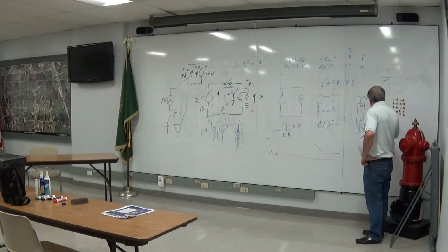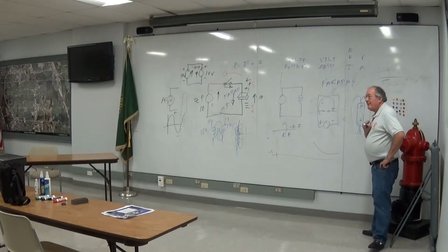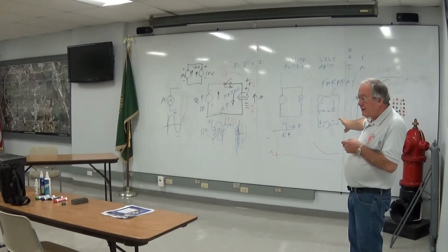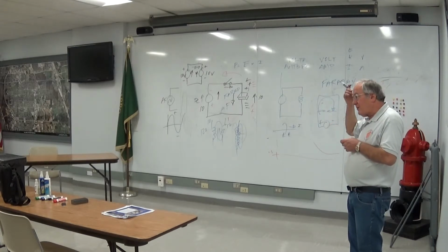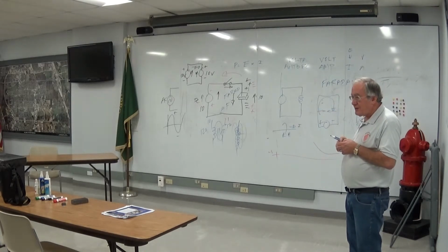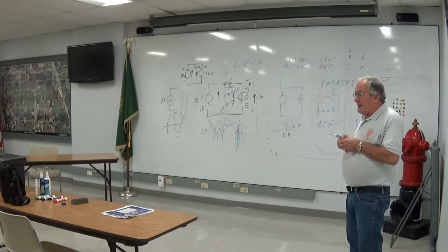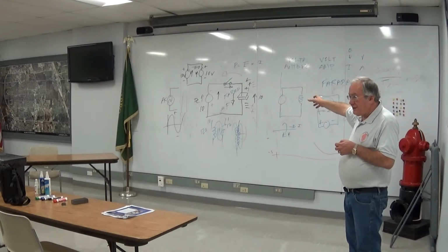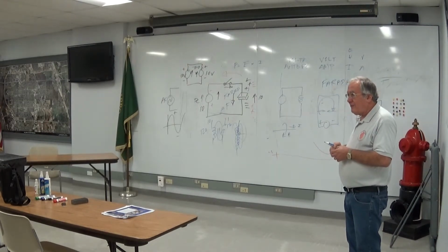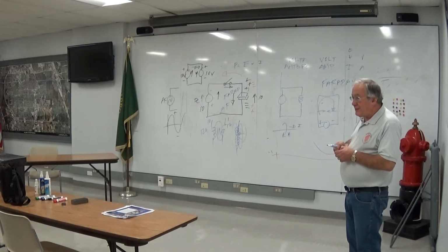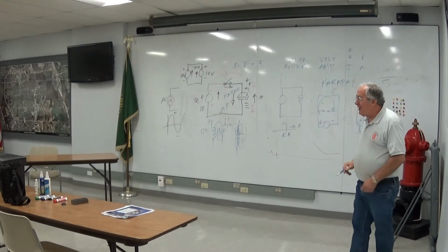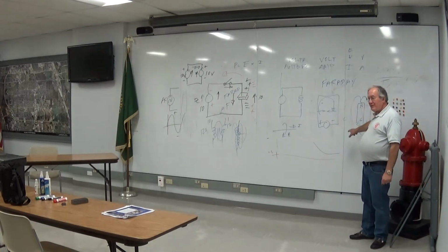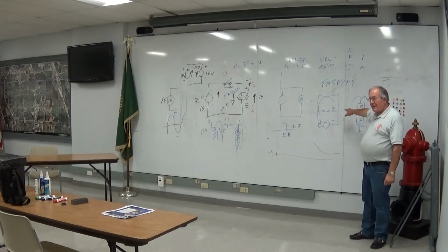They call it a galvanometer because it measures small currents. All meters measure current, even if you have a voltmeter, it measures current. We'll talk about that in this course because I will show you how a meter works. An ammeter has a galvanometer in parallel with a shunt, a low impedance bus bar that conducts at very low impedance. A voltmeter has a high impedance series resistance. Either way, they do it so that a small current will flow through the meter and the rest of it will either go, if you're measuring current through the bus bar, or measuring voltage will be cut down by the resistance.